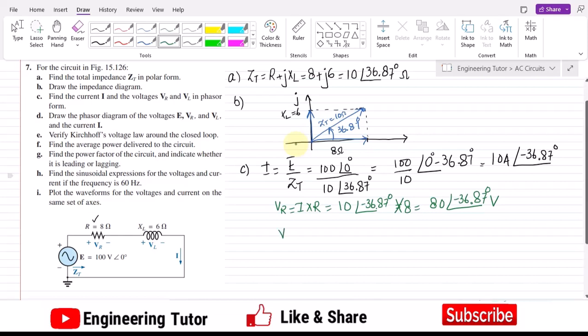Now in order to find VL, I have to multiply this with jXL, because now it has this value. The value of I is again known, and that is 10 and minus 36.87 degrees multiplied by the XL.